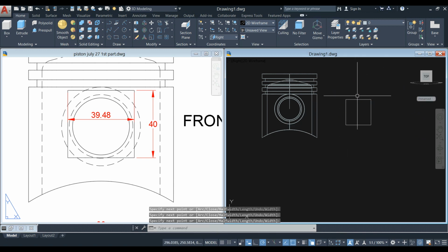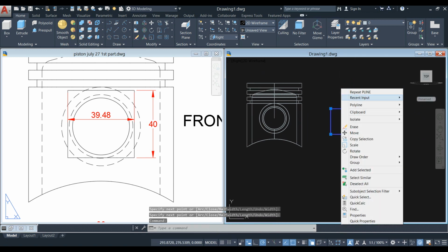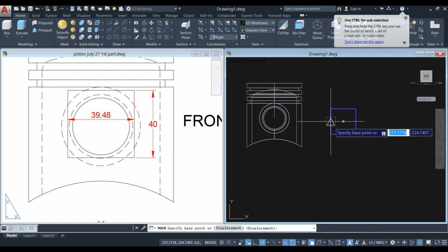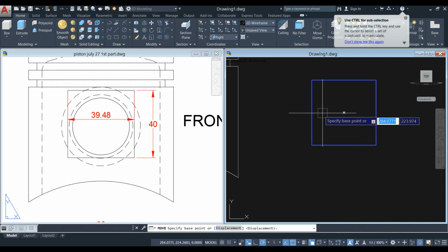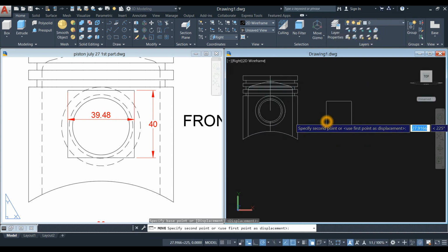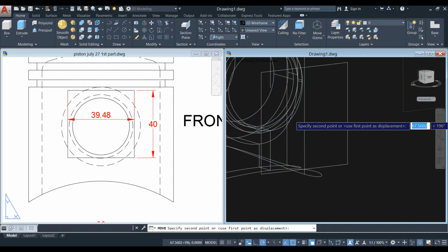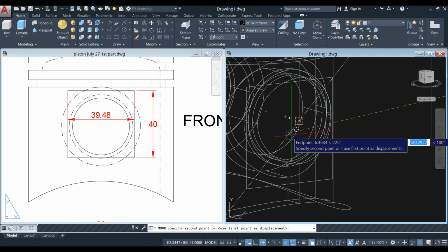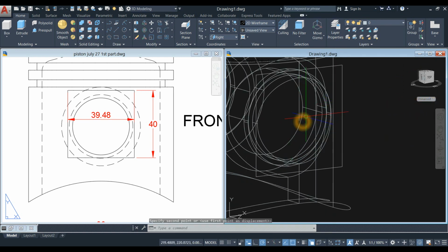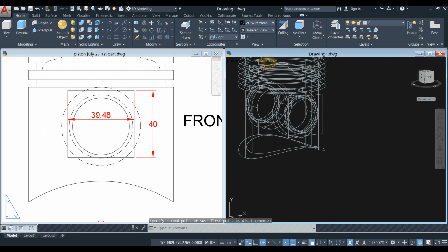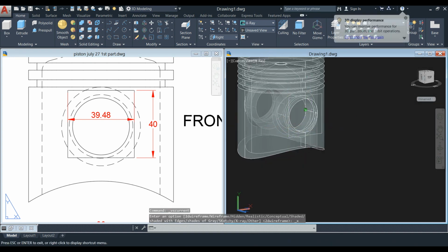Click that in point and move this object, and you can see the center of the face here. See that white thingy there? Click and attach it to the guide here. Remember, this was the center when we did the circle. I'm gonna show you using X-ray.